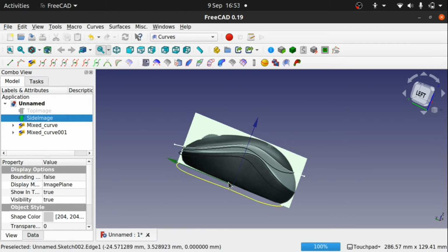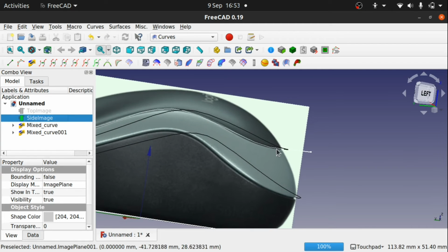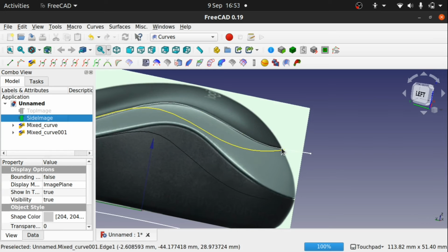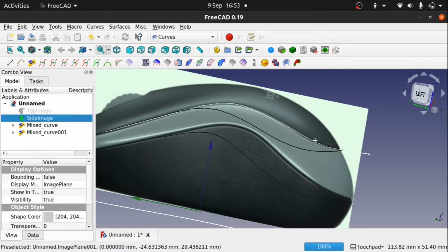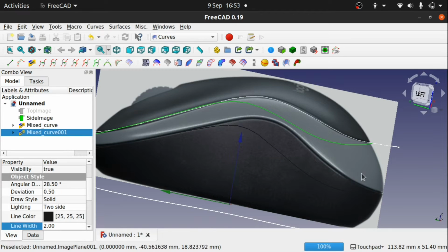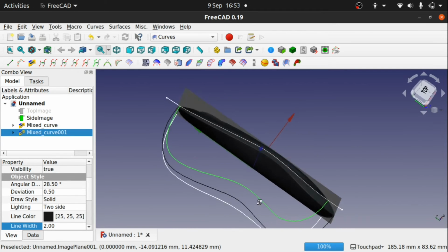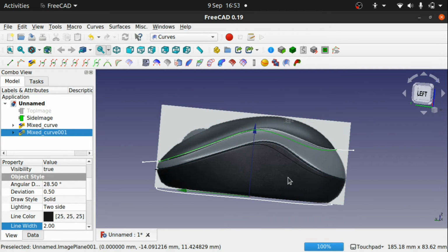Now, one thing I'm going to do is build this up with a number of curves. So where these intersect here and here, I'm going to create a curve here and here and one over the top, and also the same on the other side. The reason being because I need curves to close this feature, and also I need a curve to model the bottom as well. We're going to be using both the sweep across 2 rails and the Gordon surface for this.